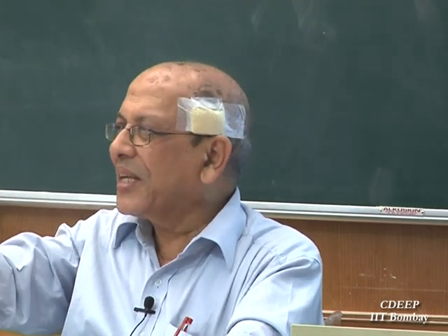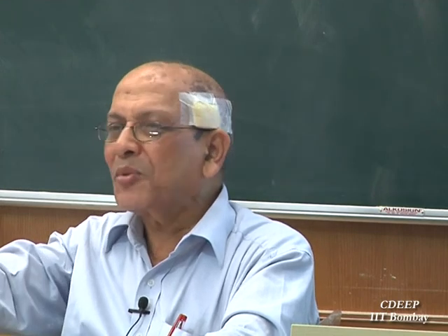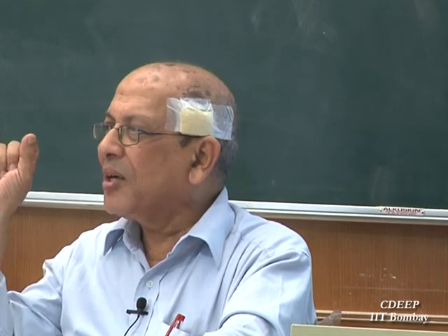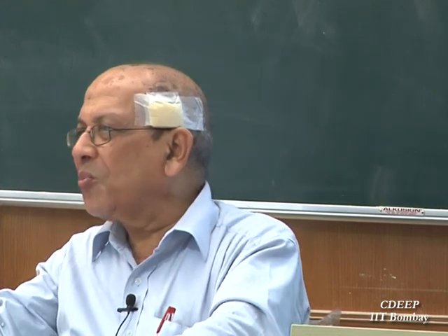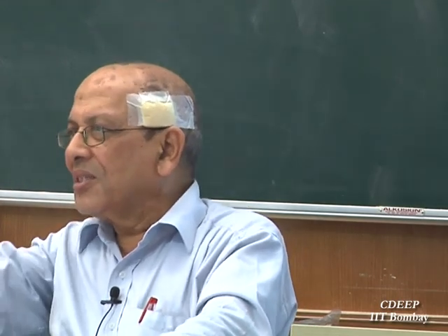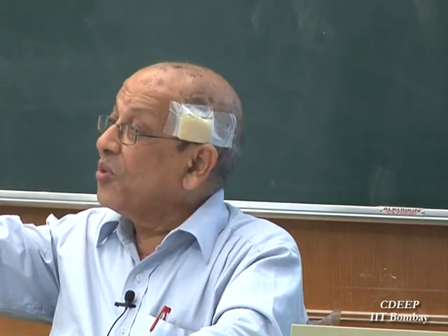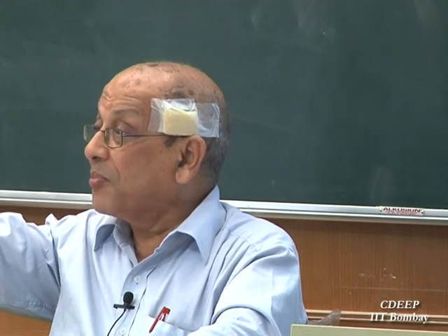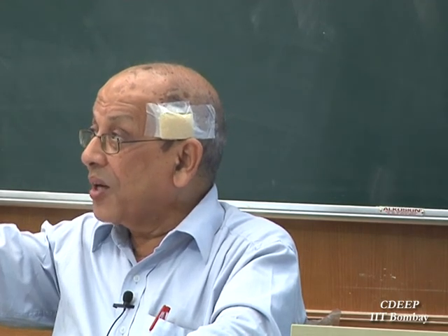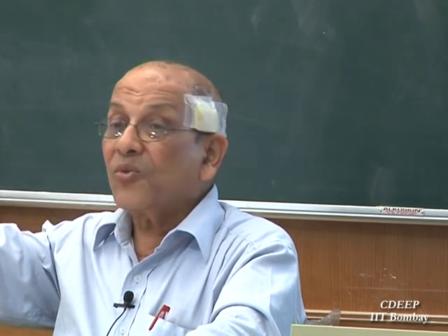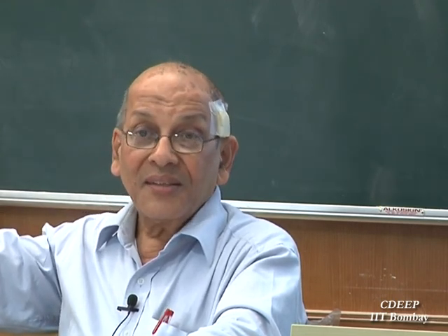Now what is the stress that will be there when it becomes plastic? The maximum stress can be only sigma y. It cannot go beyond sigma y. Ultimately you are getting a triangular loading during elastic. But once the extreme fiber becomes plastic and then the inner fibers start becoming plastic, that value will remain equal to sigma y only.